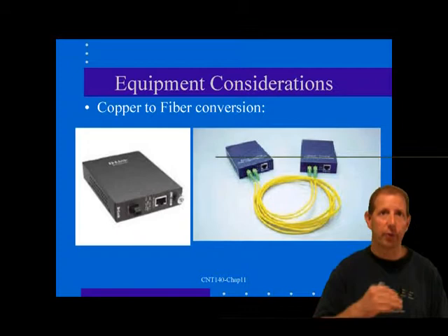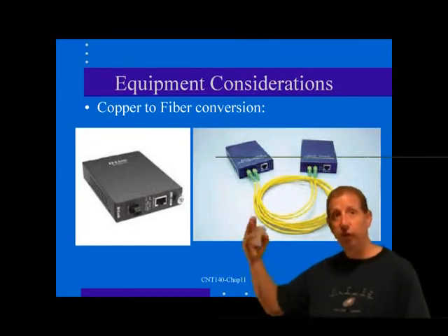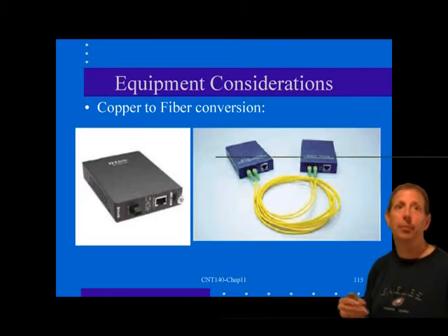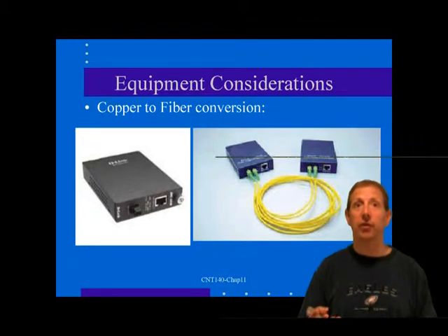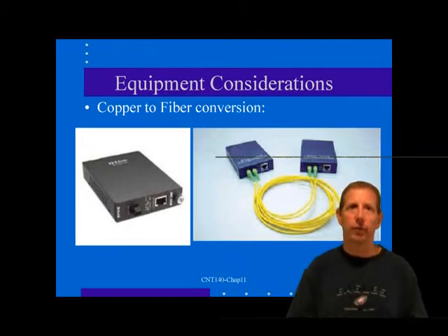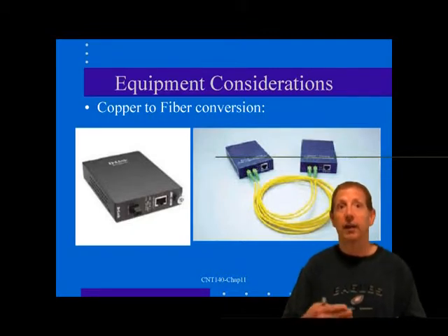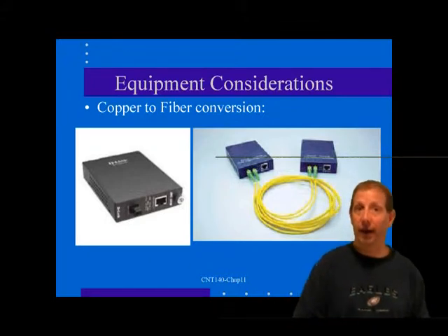In addition to the copper to fiber converters, fiber mode converters are available. As the figure shows behind me, because of the common connectors, nothing physically prevents the interconnection of single mode and multi-mode fibers. However, the connection will cause an excessive transmission loss if the optical direction is from multi-mode to single mode. There is still an unexpected loss from single mode to multi-mode, but it is not as great.